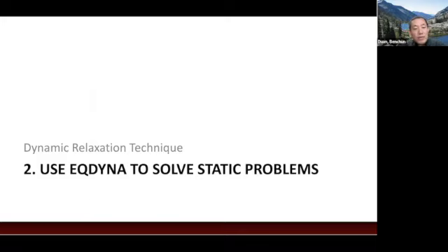After I moved to Texas A&M, I tried to extend our dynamic simulation into multiple cycles. Basically, I tried to extend it to solve the quasi-static problem of earthquake cycles, basically between dynamic events. And here I just introduce one of the methods we developed. This still sticks with our EQdyna dynamic solver, but we try to use the dynamic solver to solve a static problem. We make use of a technique called dynamic relaxation.